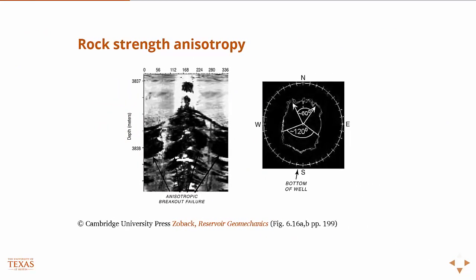So the effects of temperature can have a small effect on breakouts. I mean, something that we should consider. Also, the anisotropy of the rock strength. When we were talking about failure models and strength of rock, we at least qualitatively mentioned the effect that anisotropy can have. Anisotropy typically comes from weak bedding planes in the rock. Most rocks are sedimentary or laid down over time, and so there's almost ubiquitously some sort of direction that has a more significant strength than the other, especially when fractures are considered as an overall consideration of the strength of the rock.